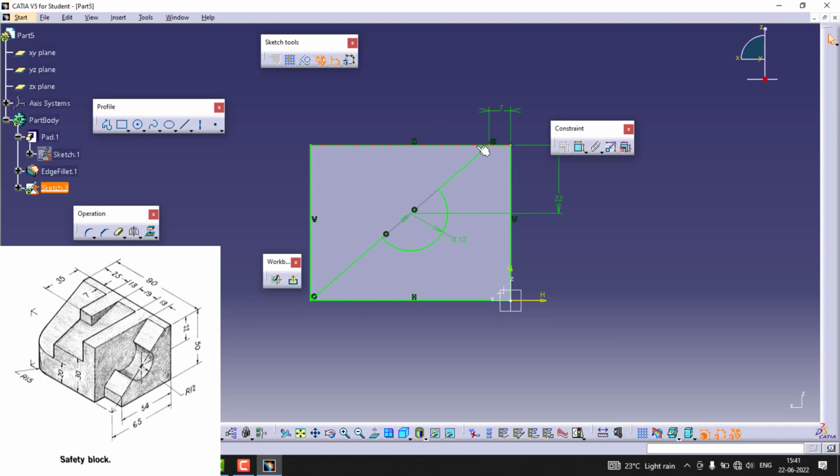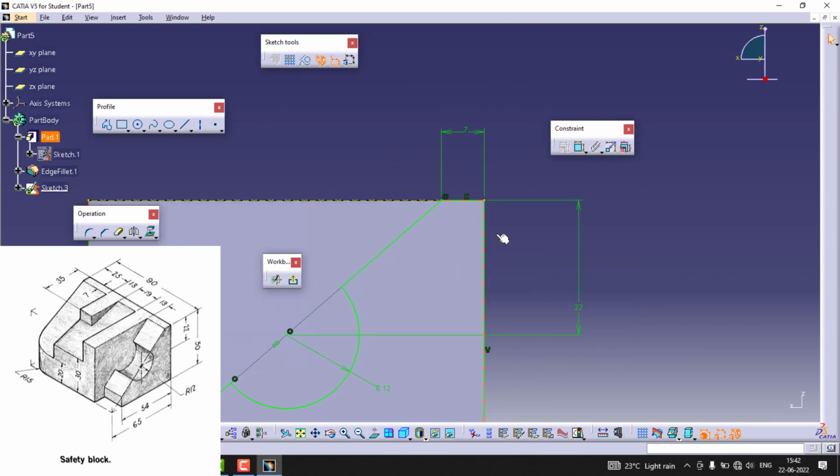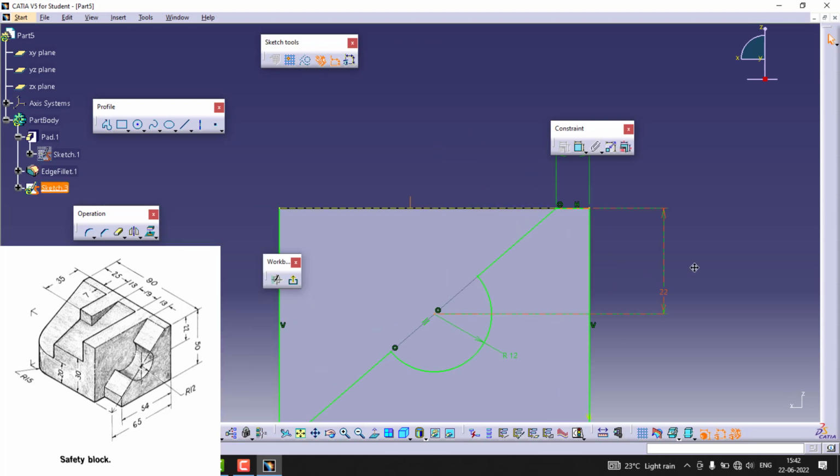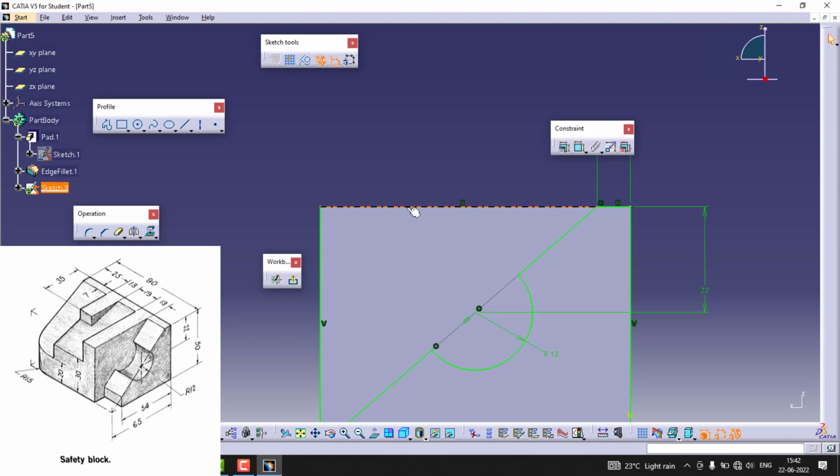At the corner we need to cut out that. I can do it later. So you cannot simply split the point. So what you can do is you can simply create 2 lines, as I said, to create the multi-pocket or multi-pad. You cannot simply draw this straight line where they intersect each other. So we can draw a line which should join these. It's a very important thing. Okay.